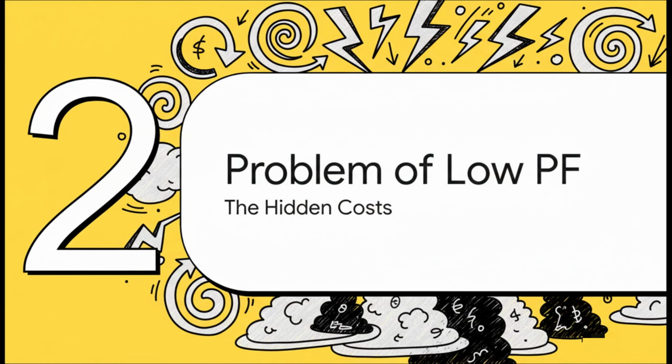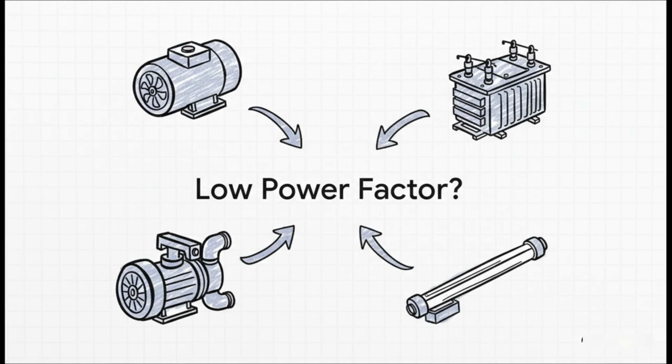Okay, so that brings us to the heart of the matter, the big problem with a low power factor, which comes with all sorts of hidden and not so hidden costs. So what are the usual suspects here? Well, the number one cause is something called inductive loads, and these things are everywhere, especially in commercial or industrial settings. We're talking about motors, transformers, pumps, fans, even older types of lighting. All of this equipment needs that reactive power to build magnetic fields, and that naturally drags the power factor down.